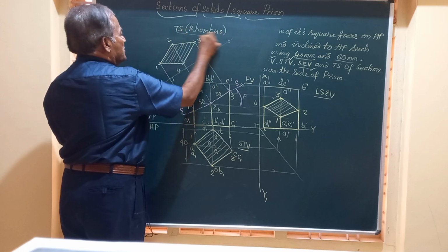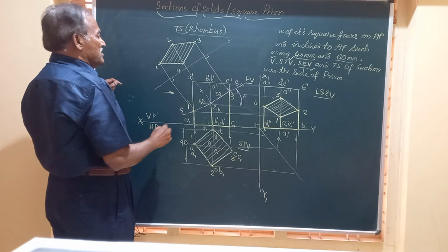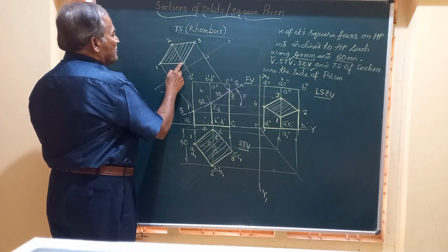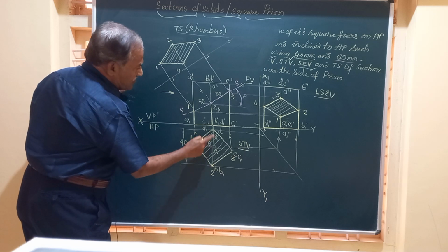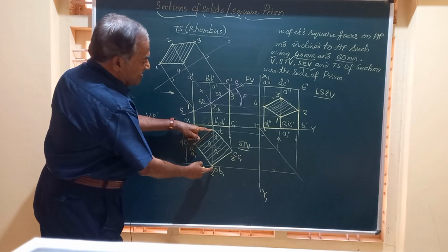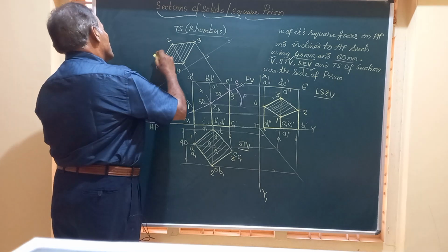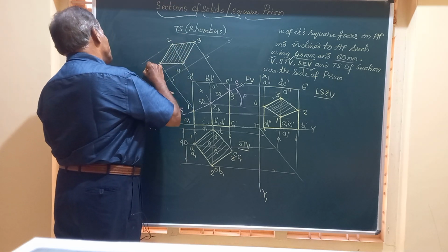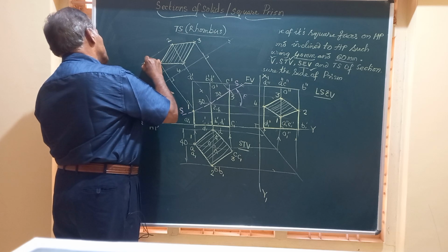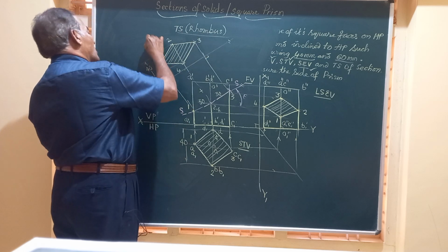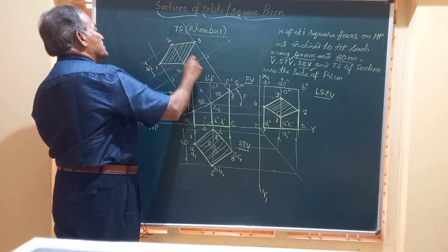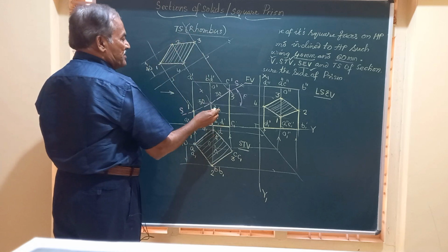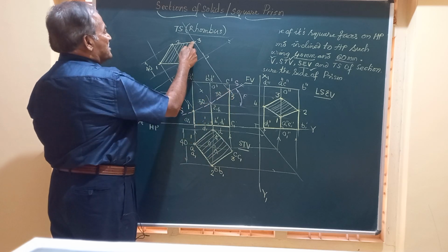So this is a rhombus, and friends, this rhombus will have the dimension. So this value from 4 to 2, 4 to 2 is nothing but that is 40. So we are going to have this as 40 millimeter, and the dimension perpendicular to that, or the longer side of this, will have a dimension 60 mm, because this distance is same as this.